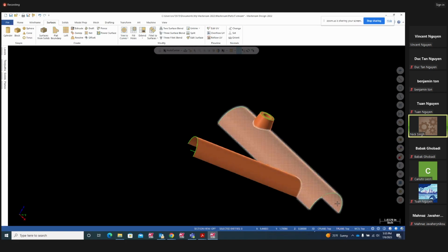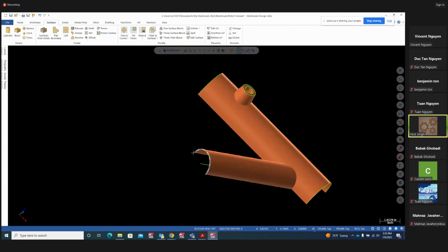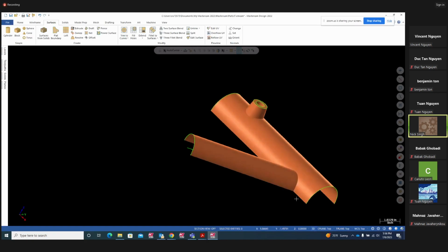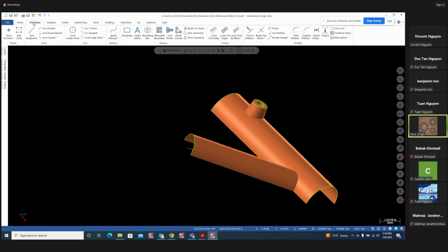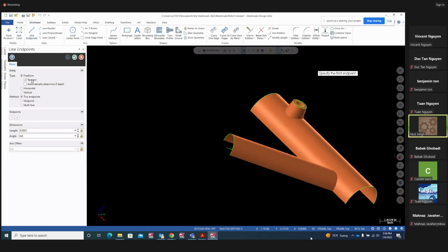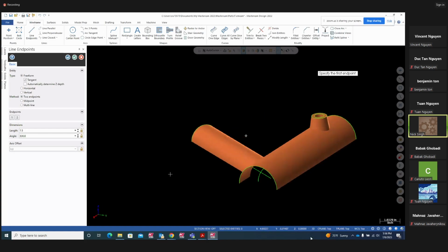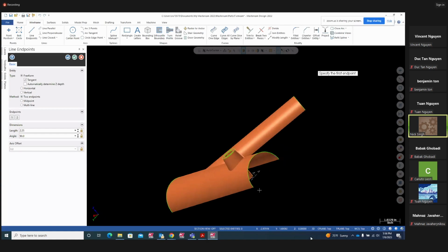Click on 3D because the X and Y points over here are going to be different, so they're all in different planes. In that case, we go 3D, and we can just go ahead and wireframe, create line. That's my freeform line. So I can join from there to here. Then I can join this guy to here. And I can join back over here too, right there.